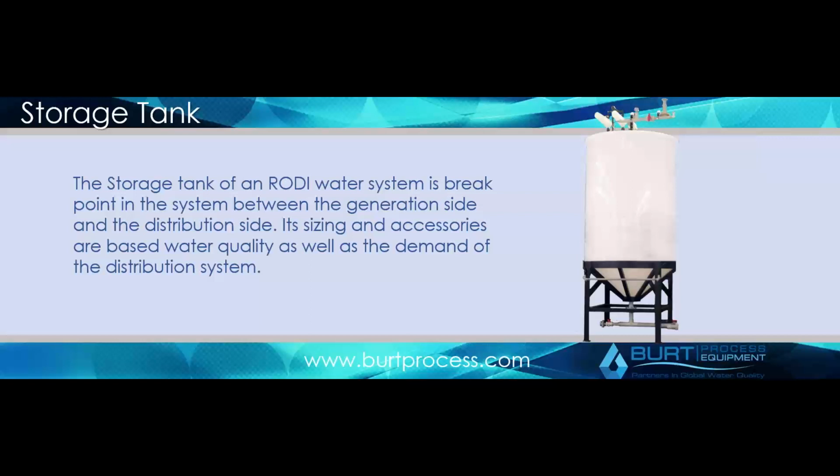For high-purity water systems, the sizing of the storage tank is not super critical. A lot of times people like to say they want to store a lot of high-purity water. That can be challenging at higher water quality, because it's very hard to keep a large volume of water very clean, even when you have a recirculation going on in your system.